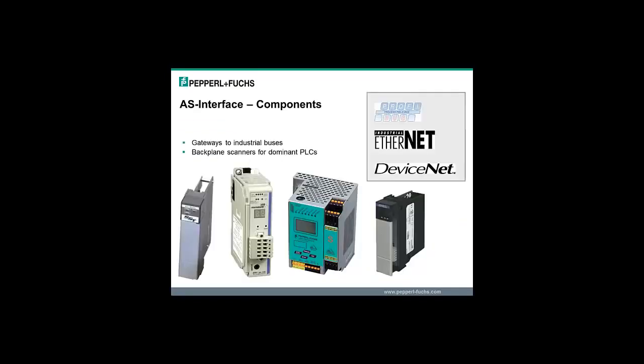Gateways are devices that couple an AS interface network to an upper-level network. This setup is a very powerful way of working with AS interface, since just about every PLC supports some kind of upper-level networking solution. The most common solutions for North America are Ethernet IP, DeviceNet, and Profibus. Of course, we also offer other solutions including Modbus, CC-Link, and Profinet. From the PLC's point of view, a gateway is a remote I/O rack with lots of inputs and outputs.